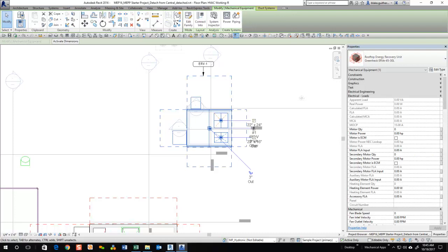In this video, we'll be talking about the enhanced smart electrical connector that has been included with all the mechanical equipment families. This was in part due to development for this shared model coordination and utilizing as much common data between mechanical and electrical as we could, thus eliminating any duplicate information which can lead to errors. What I'm going to show you is specifically optimized for a shared mechanical and electrical model, and it starts with mechanical just filling in your own information.